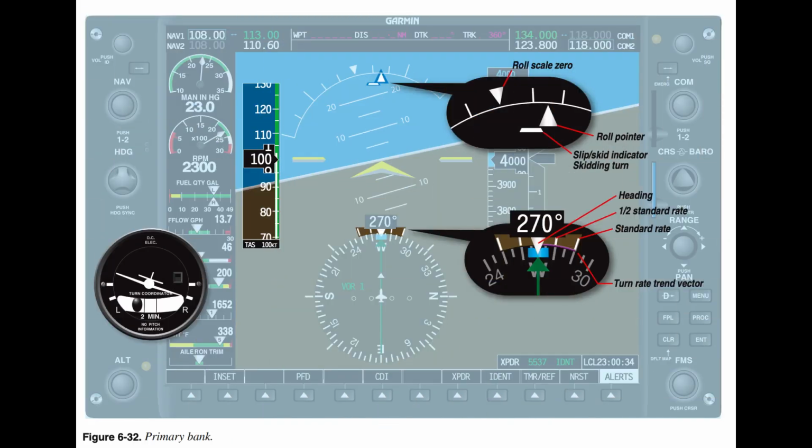When flying in IMC, pilots maintain pre-planned or assigned headings. With this in mind, the primary instrument for bank angle is the heading indicator. Heading changes are displayed instantaneously. The heading indicator is the only instrument that displays the current magnetic heading, provided that it is matched to the magnetic compass with all deviation adjustments accounted for. Figure 6.32.